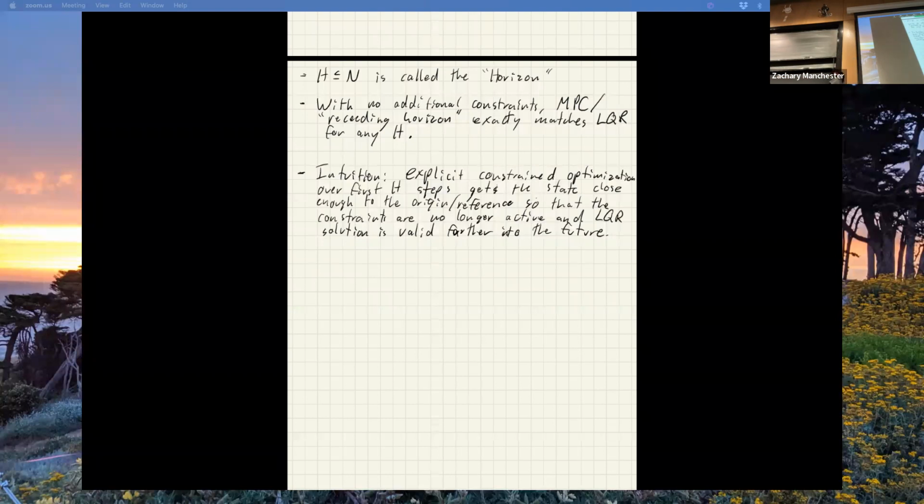So when you do MPC, you always need some cost to go approximation at the tail of the MPC horizon. It can be a bad approximation, but you always need something there to approximate the long tail, right? Because you're basically doing this myopic optimal control problem, and you need something to inform what the tail is past the end of the horizon in general. You need some cost to go approximation. This is the intuitive thing in this LQR context, but in general, you always have to have something there.